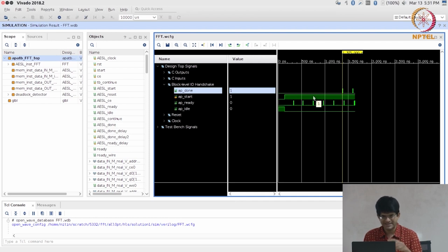FFT call, it still puts it in a loop until it is able to at least measure the one done signal. Okay. So, if for whatever reason your Verilog code hangs and is not terminating, not generating a done signal, your simulation will go into an endless loop, right. So, there can be situations where you don't even crash, but just sit there simulating endlessly. Okay. So, those are all things that you need to be aware of and catch if necessary. But this very clearly indicates the difference between latency and the pipeline initiation interval also.